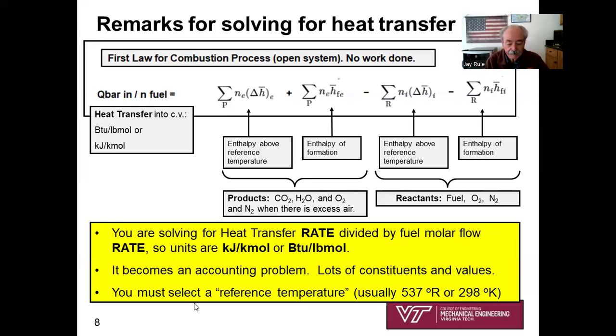You, the engineer, have to select a reference temperature. Now, this is a little easier than it appears. If you're in English units, you're typically going to select 537 degrees R, which is a standard temperature in the combustion world. I believe that's 77 degrees F, right? So that's sort of a standard for combustion problems. And over here in metric, you're going to select 298 degrees K as your reference temperature.